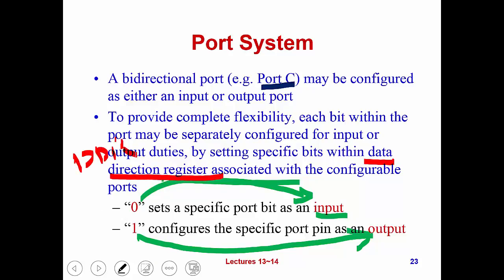So each port has a corresponding DDR. They're mainly designed for us to configure the port. So we can configure the port to be input port or output port, or input channel or output channel, by programming or setting a specific value of this data direction register.